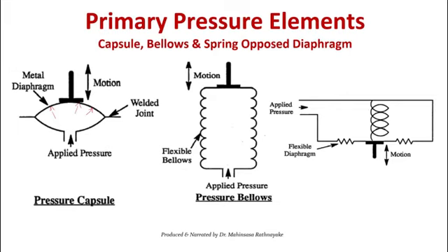We have to use a special material for this, which can be called a membrane type material, that displaces with respect to the pressure, right? Then of course this motion can be measured, right? So there is a direct relationship between this motion and the applied pressure.